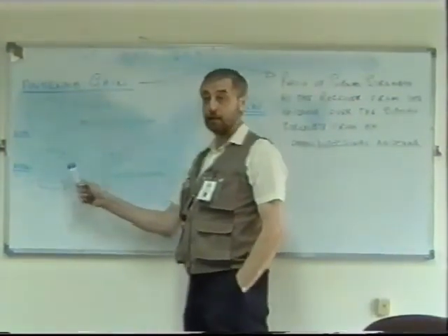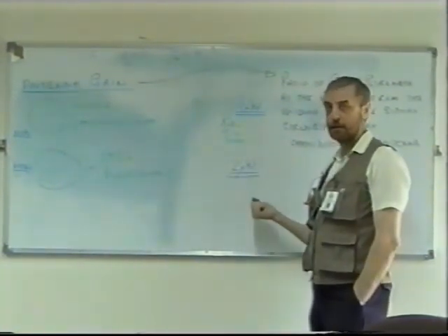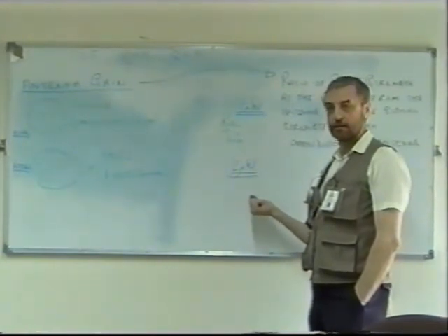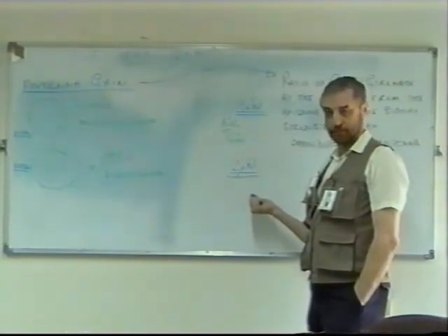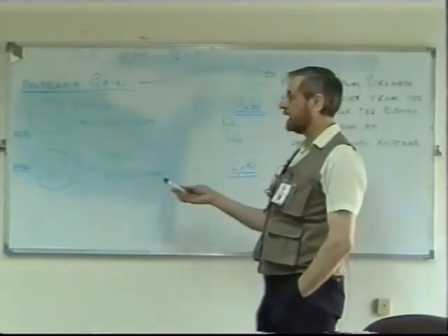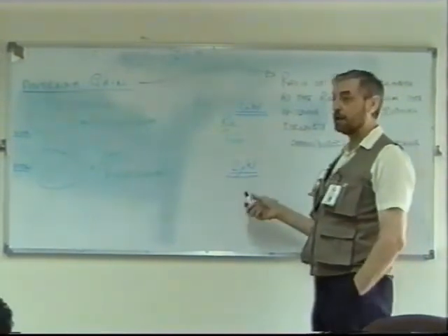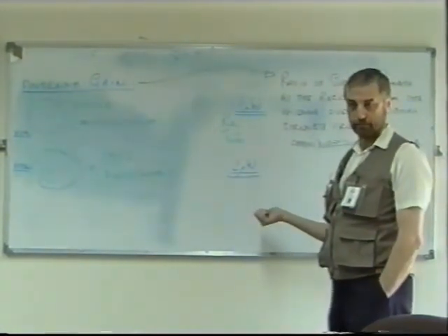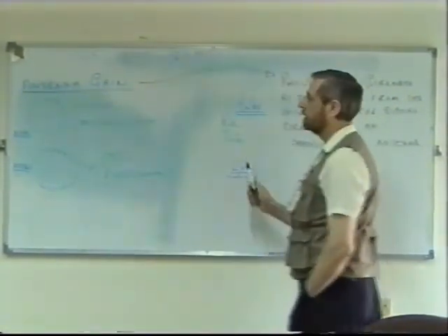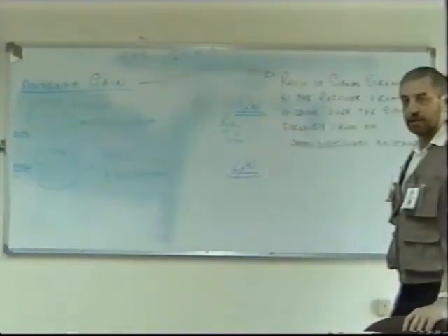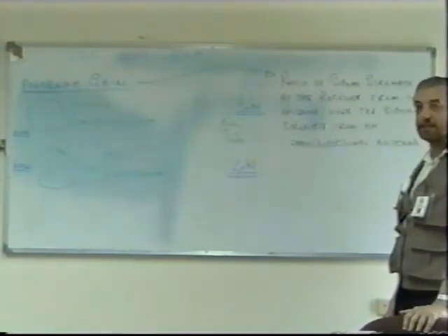If by using a Yagi I get twice the power compared to using an omnidirectional, then how many decibels is this? 3. 0.3 times 10. In other words, we say the antenna gain of the Yagi in this example would be 3 dB. Normally the antenna gain is much more than 3 decibels. That's an example where you've got twice as much power in your receiver compared to that from an omnidirectional. 3 dB, as we mentioned last week. Yes, we say the antenna gain is 3 decibels.